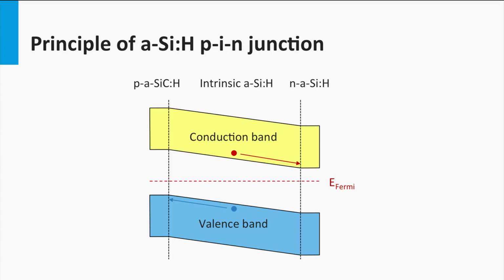Note that as the absorber layer is intrinsic, the charge carriers neither belong to the minority nor majority charge carriers. The hole and electron density is in the same order of magnitude. In the P layer, the holes are the majority charge carriers and the dominant transport mechanism is diffusion. In the N layer, the electrons are the majority charge carriers and diffusion is the dominant transport mechanism.